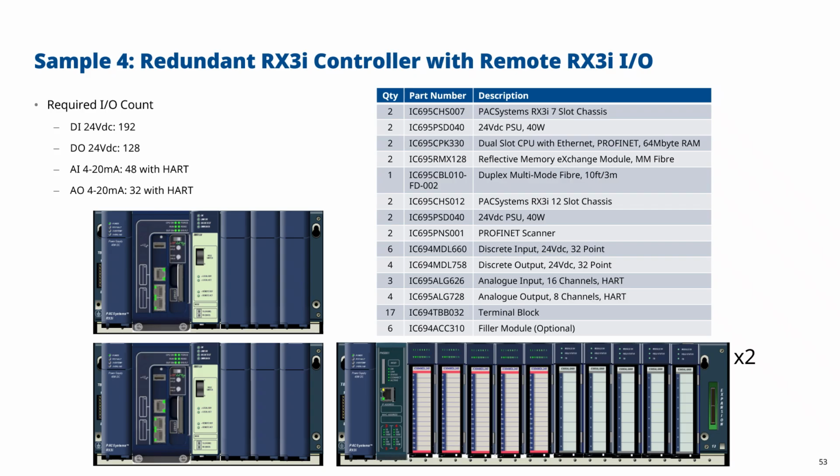And what we could probably do is explain to the client that there is this issue of dual fault tolerance, whereas if you get 2 failures, you might have redundantly or separately controlled I/O. But if they're willing to live with that, then we can keep the bill of materials for the CPUs quite simple. So again, no separate PROFINET controller because I don't have much remote I/O.